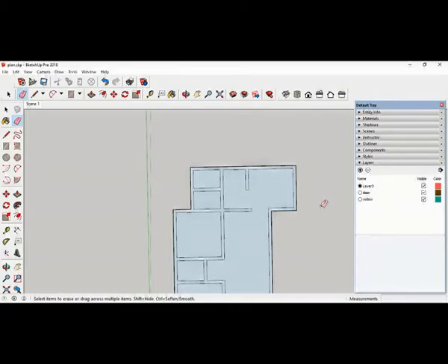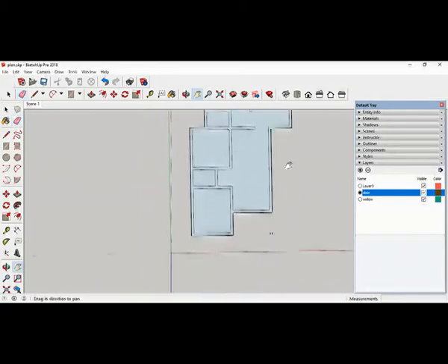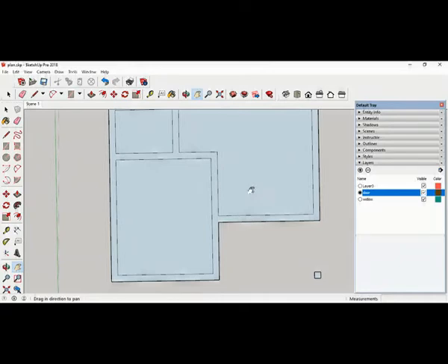So now we are going to create the doors. So I will go to door layer. Okay, so we'll start from here. Again, tape measure tool. I will draw a line. The door I'm keeping 10 centimeter away from here. So 0.1. My door width is 1 meter. Now from here, I want to keep the window 20 centimeter here, 0.2. And this window is 1 meter.